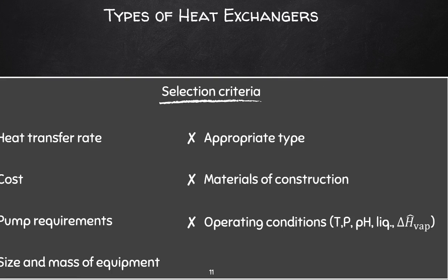So how does one go about selecting the type of heat exchanger? Overall, first off, you should consider the application. How much heat is required to be transferred? If heat transfer requirements aren't very large, then go with the cheapest and simplest option, such as a double pipe heat exchanger.